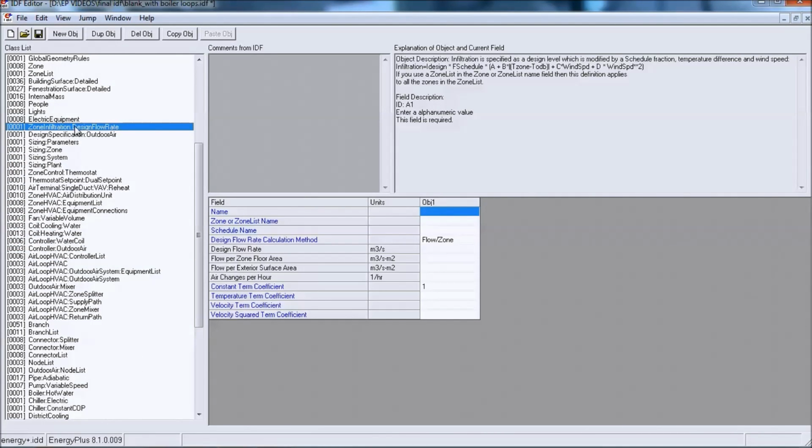making the remaining objects. The very first is making zone infiltration. Zone infiltration design flow rate is used to tell EnergyPlus about the small leakages inside a zone. It can be small leakages in windows, below or above doors, small holes inside walls. It can be anything infiltrating inside.